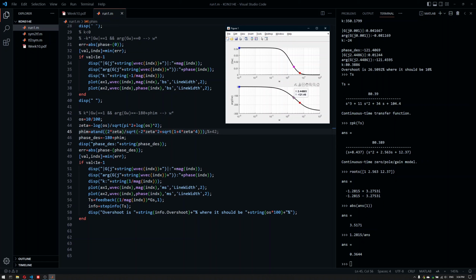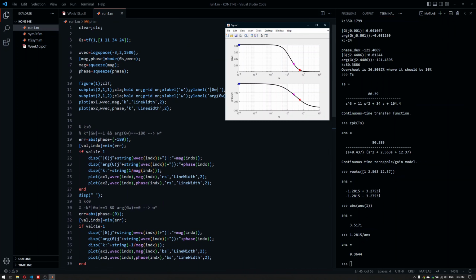The disadvantage here, the bad thing about frequency methods is that we are not really relying on the transfer function that much. We are kind of using the Bode plot or Nyquist plots, etc., all the frequency domain methods on their own. And as you will see in the upcoming parts, it doesn't really matter what the Bode plot is, or where the Bode plot is acquired from, what kind of transfer function or system it is from. It doesn't really matter. The rules stay the same. You look for basically the same stuff. So yeah, it's a nice tool because you can apply it to a wide variety of systems.